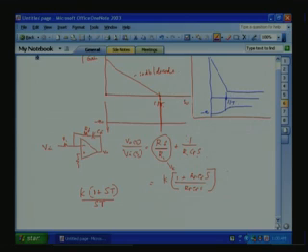So, by placing this in the overall closed loop control, the phase margin at the gain crossover we can adjust. So, both the gain as well as the phase shift we can control. This will also have 0 steady state error because of the integrating element here.